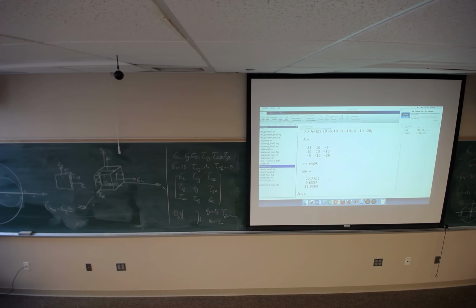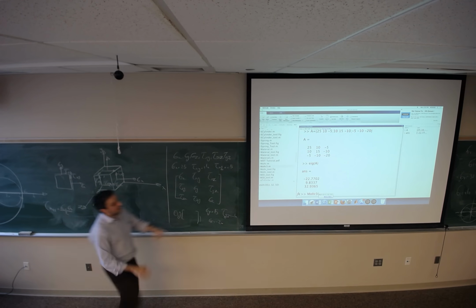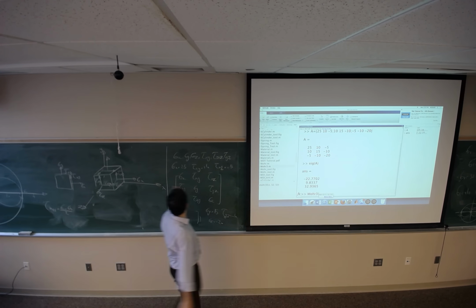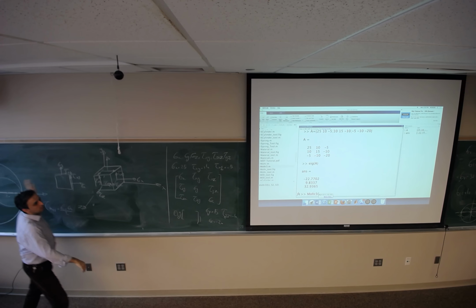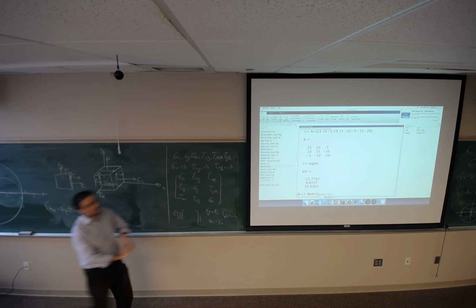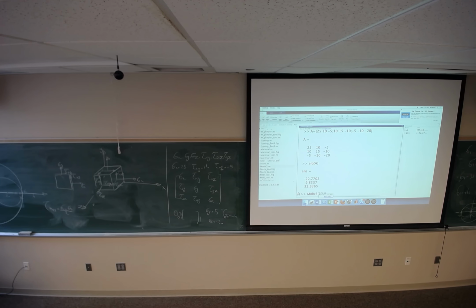If you just type Mohr 3 parentheses and enter the 3 values of sigma 1, sigma 2, and sigma 3, it's gonna draw the 3-dimensional Mohr circle for you. So sigma 1 is 32.93 in this example. Second one is 9.8, and the third one is negative 22.77.